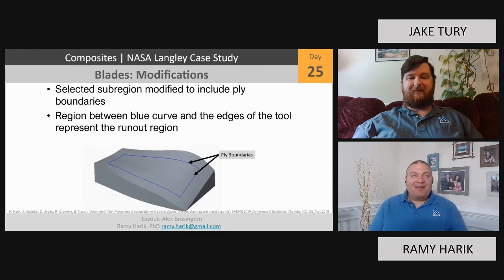So definitely making a tool out of a material such as Invar or so on is the best way to go, but not if you're starting a new project and you are exploring. If you're starting a new project and you are exploring, the best thing to do is to create a tool form with 3D printing, and we're going to talk a little bit about that.